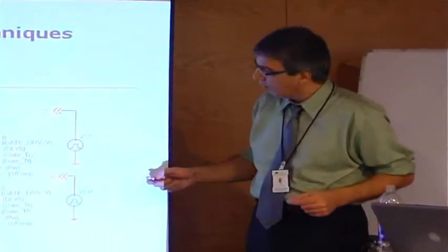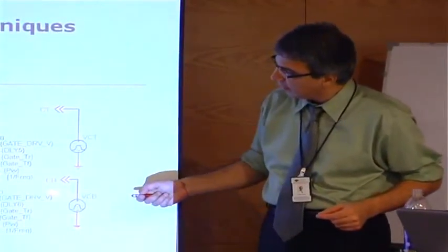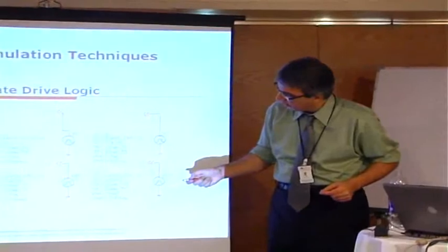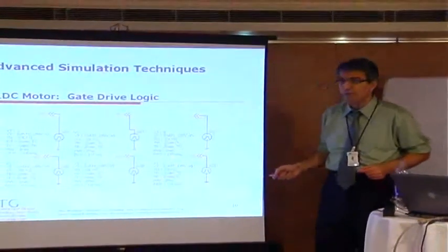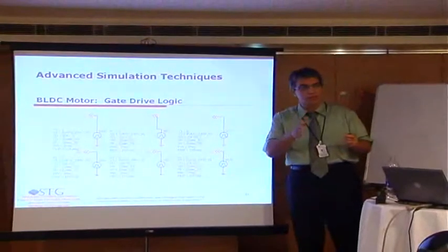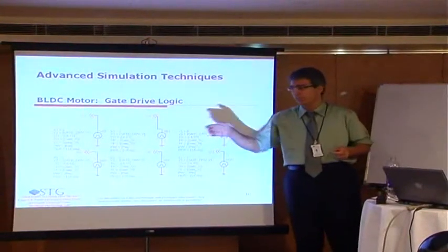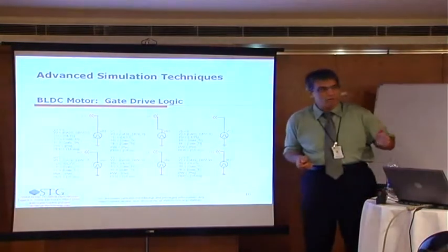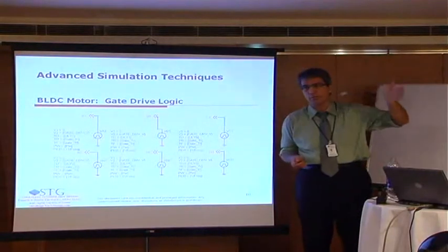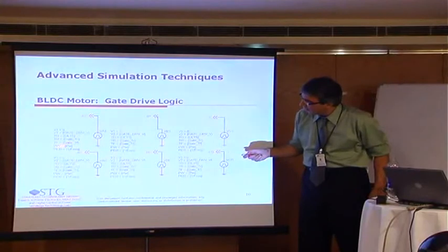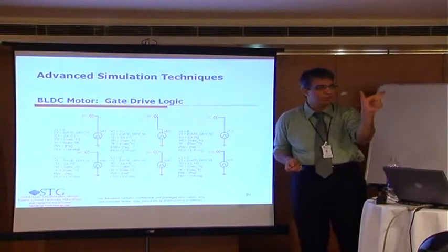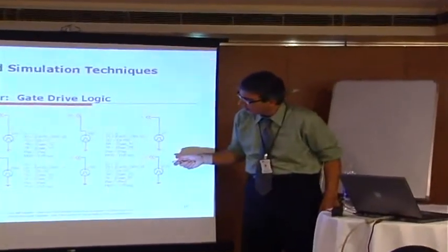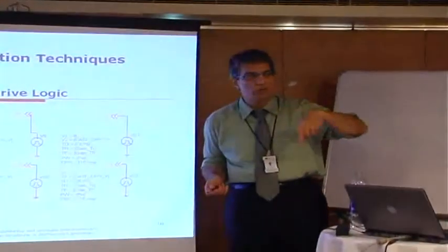Okay, as you can see, there are basically 6 delays: delay 1, delay 2, delay 3, delay 4, delay 5, delay 6. So these delays sequence when these gate drives come on. And then the rise time and the fall time is how fast is the rise and fall of these square waves. And then PW is the pulse width of these square waves, which is 120 degrees in this case, and the frequency is essentially the frequency of rotation of the motor.